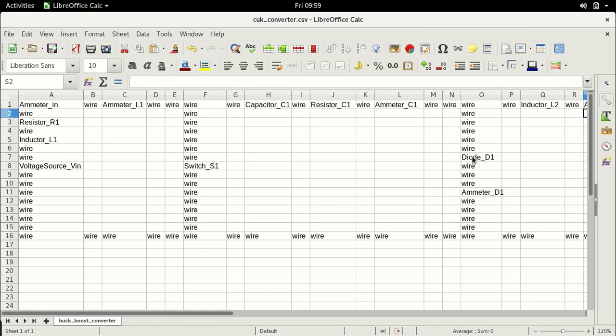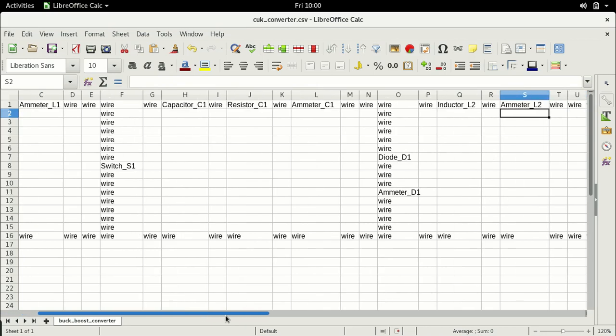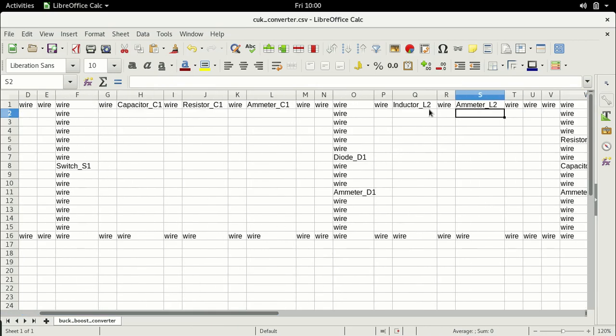This diode is connected in such a way that the cathode is pointing downwards. So the current will flow downwards, because the cathode of the diode is downwards. So this inductor will charge the capacitor through the diode. Now when the switch is turned on again, the inductor charges as always, but now the capacitor will also discharge through the switch, because remember, once the capacitor has some charge, the capacitor will also find a way to flow. That means it will flow through the switch S1. So the capacitor is going to discharge through this switch and will start charging the inductor and the output capacitor.